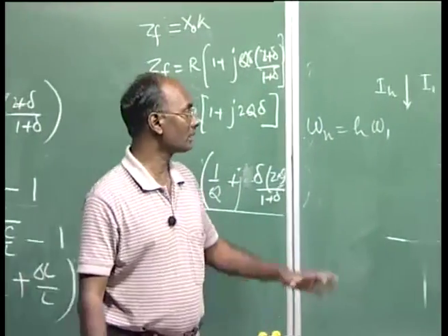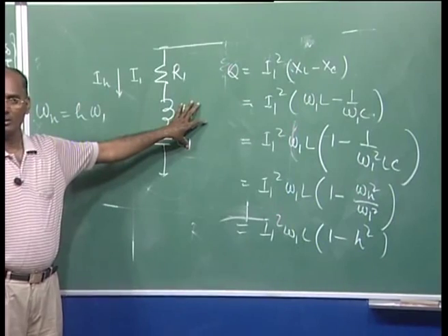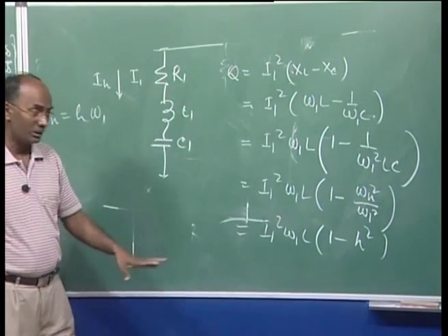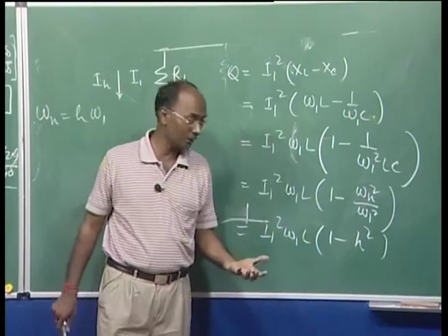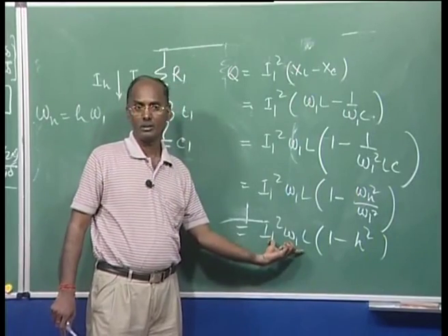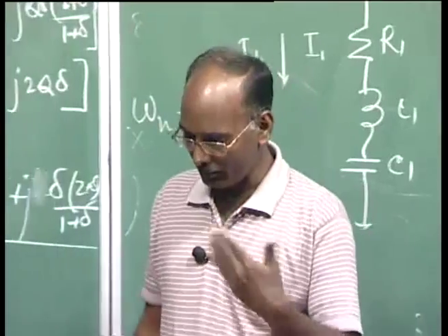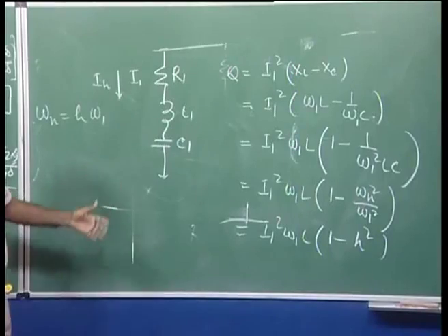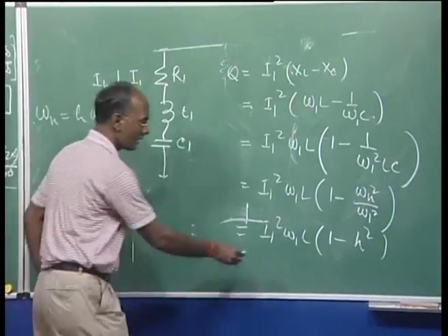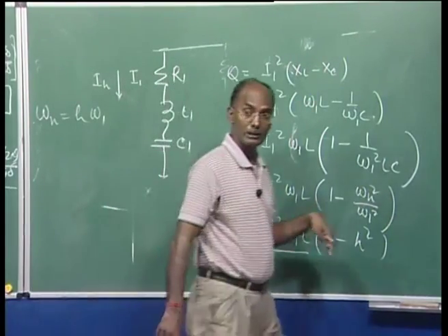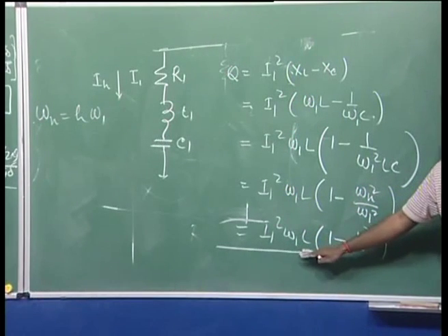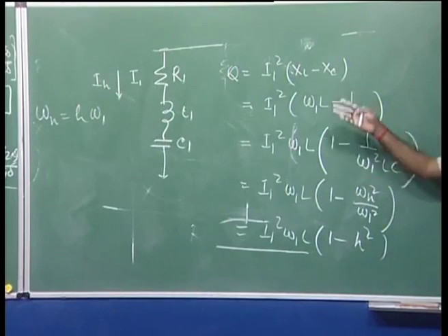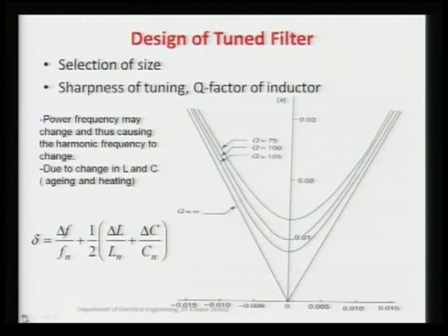What does it mean? It means this is behaving as capacitive. And you can see this is a huge amount. Now you can imagine this is a 5th component, so 25 minus 1, it is 23 times this component. So it is giving a significant amount of reactive power support that is required by the system. So this is basically, we can see the shunt filters, especially not the series filter. Shunt filters provide the reactive power support at the fundamental component. However, the series filter is always consuming. You can also verify it in a similar manner.